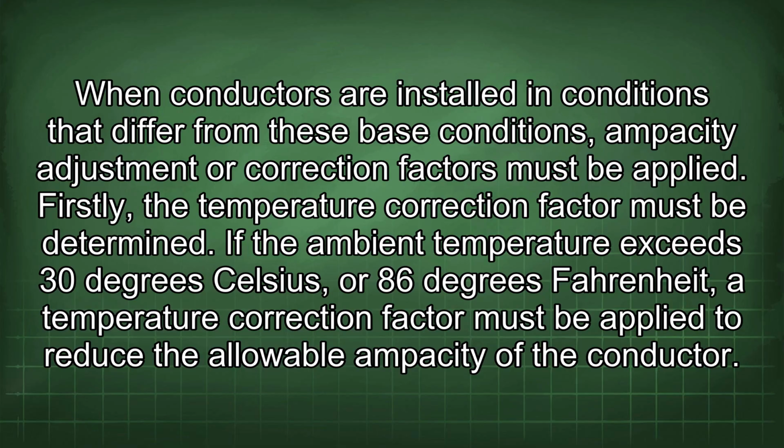Firstly, the temperature correction factor must be determined. If the ambient temperature exceeds 30 degrees Celsius or 86 degrees Fahrenheit, a temperature correction factor must be applied to reduce the allowable ampacity of the conductor.